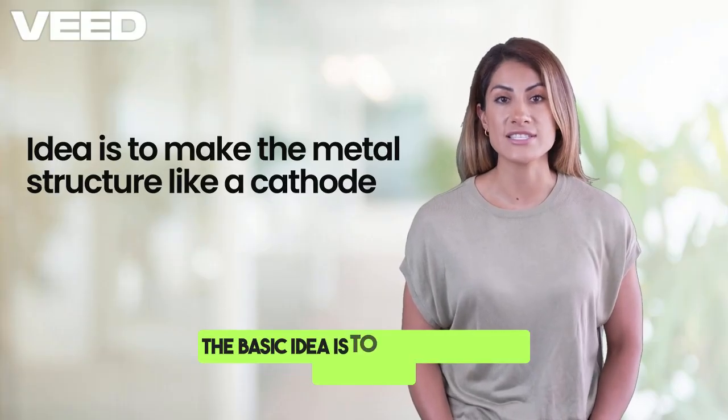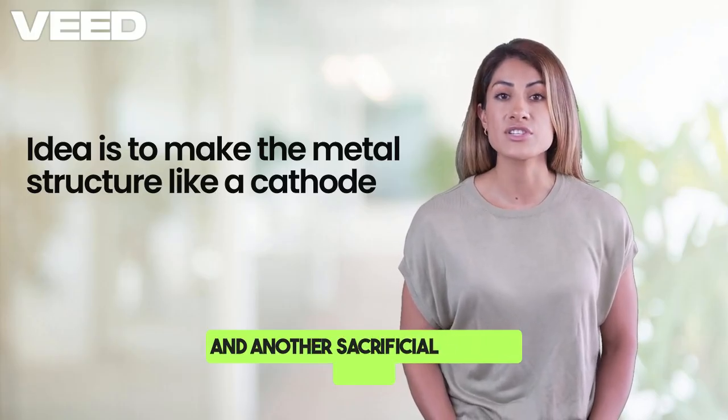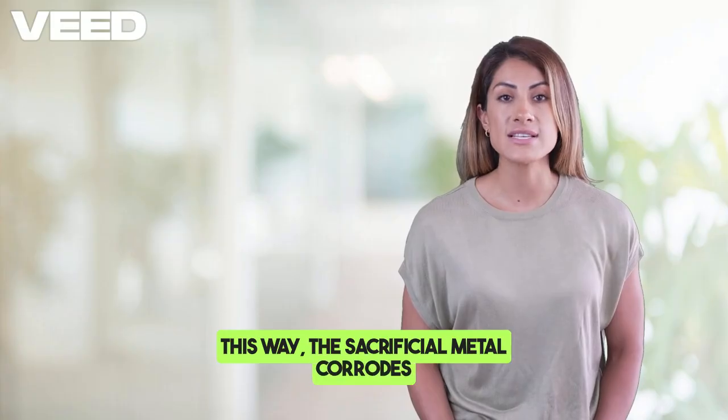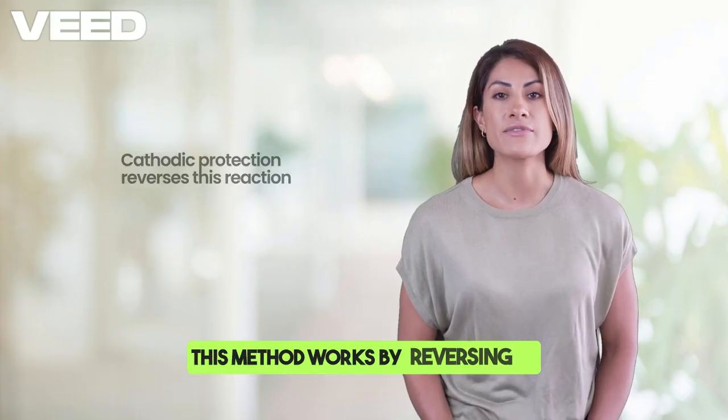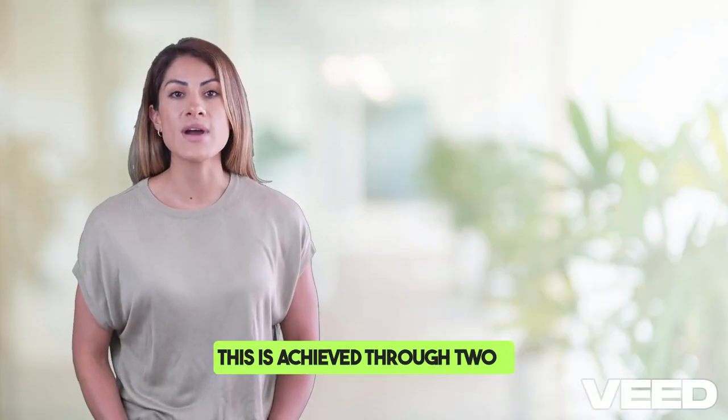The basic idea is to make the metal structure we want to protect like a cathode, and another sacrificial metal is made anode, thus forming an electrochemical cell. This way, the sacrificial metal corrodes instead of the main structure. This method works by reversing the natural electrochemical reaction that causes corrosion. This is achieved through two ways.